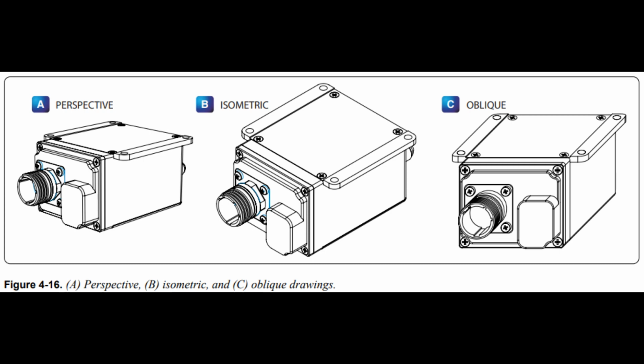Isometric drawings. An isometric view uses a combination of the views of an orthographic projection and tilts the object forward so that portions of all three views can be seen in one view. Figure 4.16b. This provides the observer with a three-dimensional view of the object. Unlike a perspective drawing where lines converge and dimensions are not true, lines in an isometric drawing are parallel and dimensioned as they are in an orthographic projection.